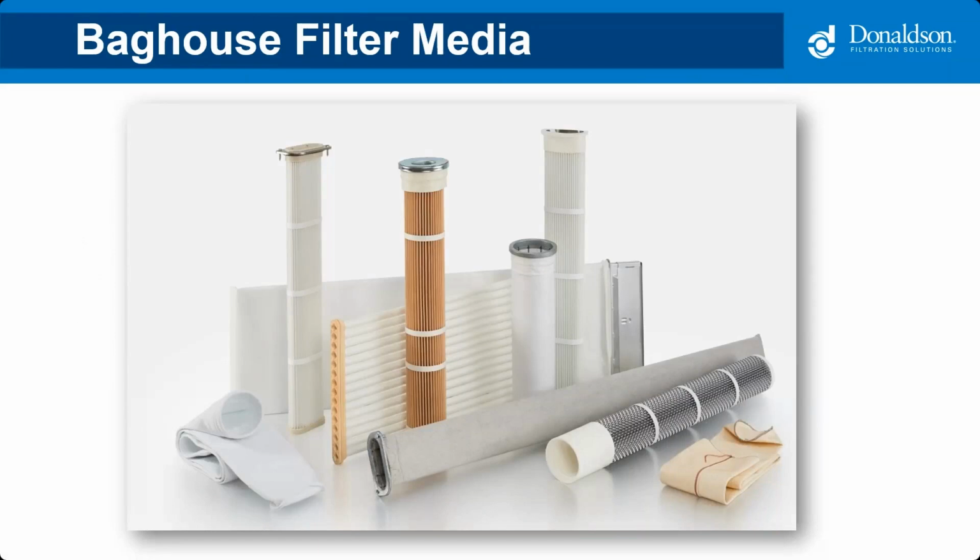Baghouse collectors use baghouse filters. The two main types are fabric or pleated. Fabric bags are installed over metal cages. During filter changeouts, the entire bag and cage are removed from the collector. The used fabric bag is removed from the cage, and the new one installed around it in its place. Then it goes back into the collector.